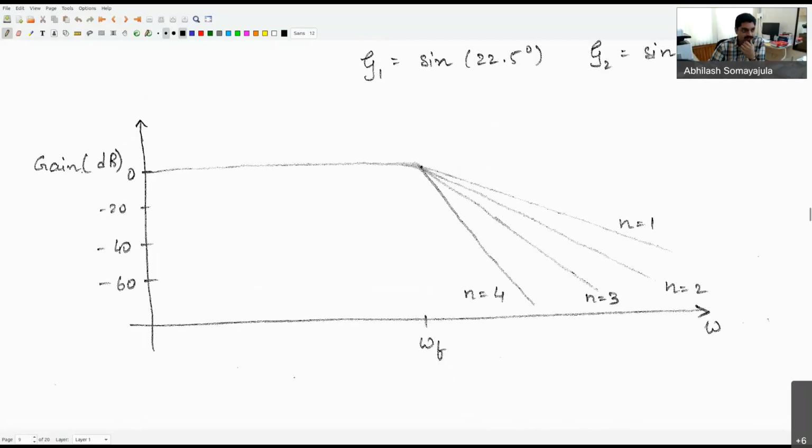And that is quite possible to do as long as we have a good amount of separation between the control bandwidth of the system and the wave frequencies. Then you can choose appropriately a cutoff frequency in between so that this can be achieved. But we also understood the problem that in case that is not the case, it may be a little more complex. So we have to deal with what happens if the control bandwidth is actually bigger than what the wave frequency regime looks like.